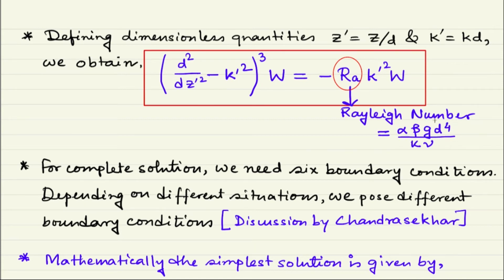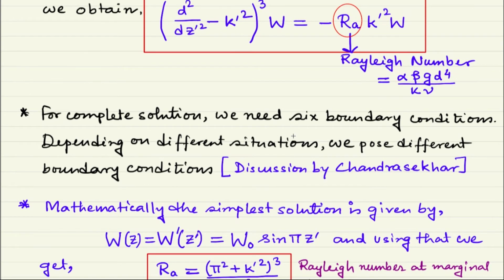So the Rayleigh number in some way basically gives you the importance of the effort of the system to make an important temperature gradient relative to the effort of the system to destroy that temperature gradient. You can easily understand that if the Rayleigh number is larger and larger, then the system can be subject to more and more convective instability.